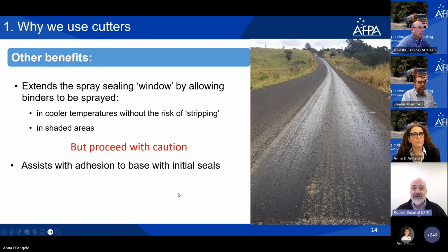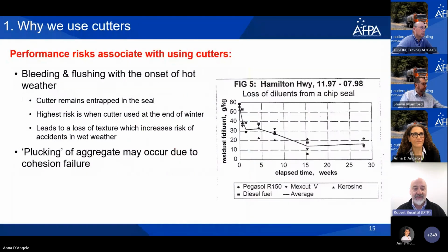Also, in shaded areas, obviously, when we're talking about cutter use and cutter addition, it's all built around temperature, pavement temperature and the ambient temperature. So we've got to consider that. But you need to proceed with caution with that. That's why, because we can get too late in the season and we start adding a lot of cutter in, which may not be a good thing. In a lot of cases, it isn't, because we end up having problems.